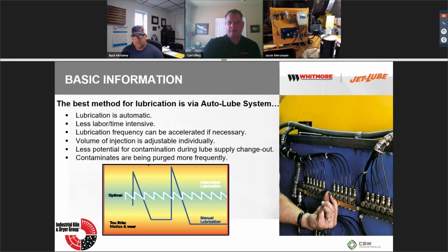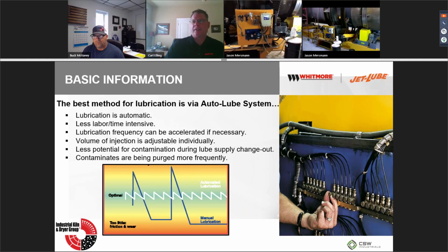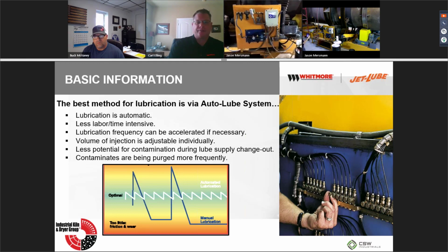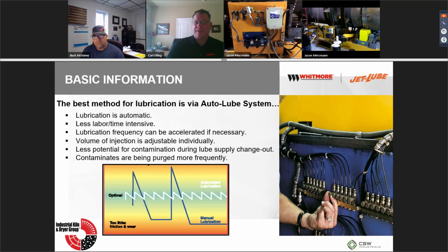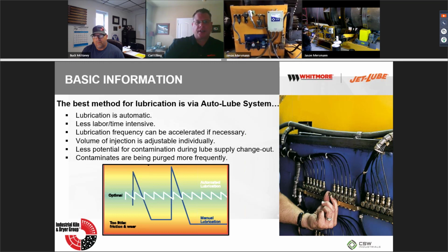So just something to consider, and you can achieve that through a single point auto lubricator or a multi-system, which is pictured over here to your right. And then also Jason's got the open gear system. Those particular things are automated lubricant systems. These all help out. It's much easier to manage this system versus doing the actual lubrication manually. So just to touch on that one.